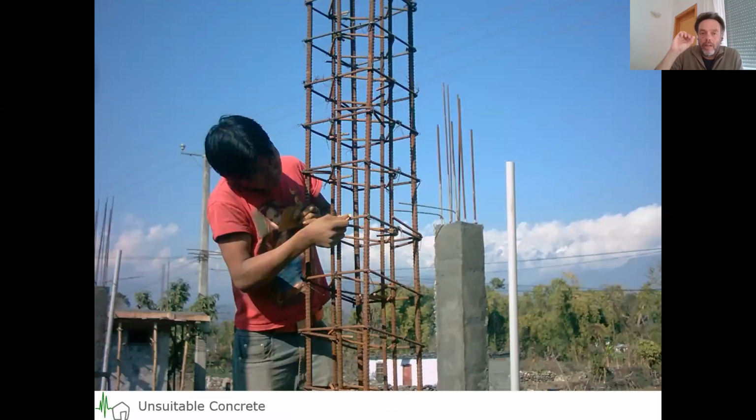Now, it is of course possible to make a concrete frame earthquake resistant. We did one, but the only reason why we did this is that we started building upon an already existing system, which was an animal center close to the city. What we had to do here is add a lot of steel. Compared to a non-seismic resistant frame, there's about 2.5 times more steel involved in an earthquake resistant frame. So you see it's quite complicated. Well, not for us, but there's a lot of detailing happening here.